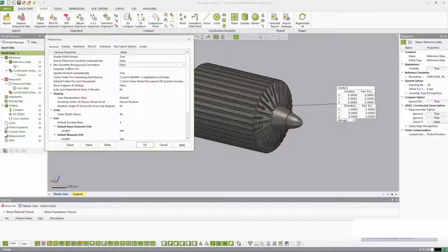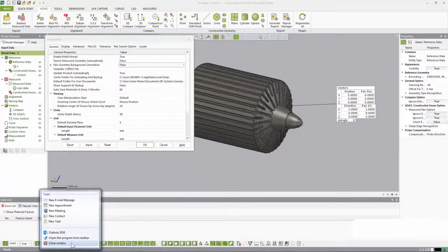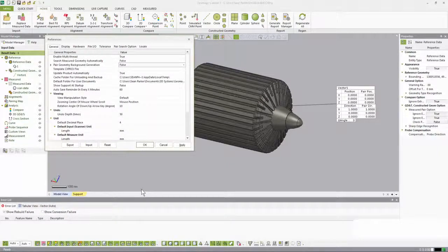These options will automatically find a pair on the scan data to every CAD face on the CAD model. That's really good for small mechanical parts, but it's not great for long-range scan data, especially when we've got really, really large files. So the tools that I'm going to use are going to create this pairing more manually.